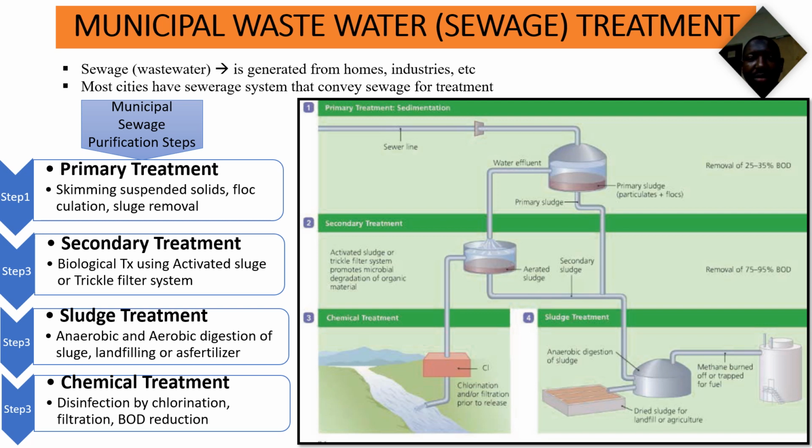During the chemical treatment method, water from the secondary treatment is disinfected, usually using chlorination, after which it can be released into rivers or oceans and recycled for drinking, or in some cities, the water can be used for spray irrigation of crops and maybe highway vegetation.